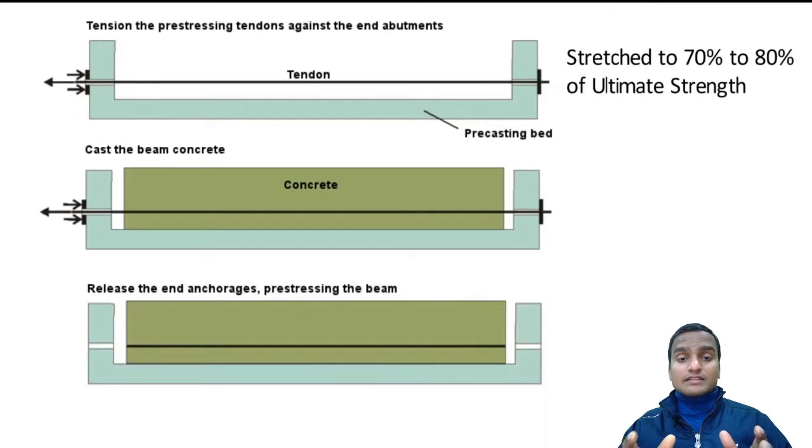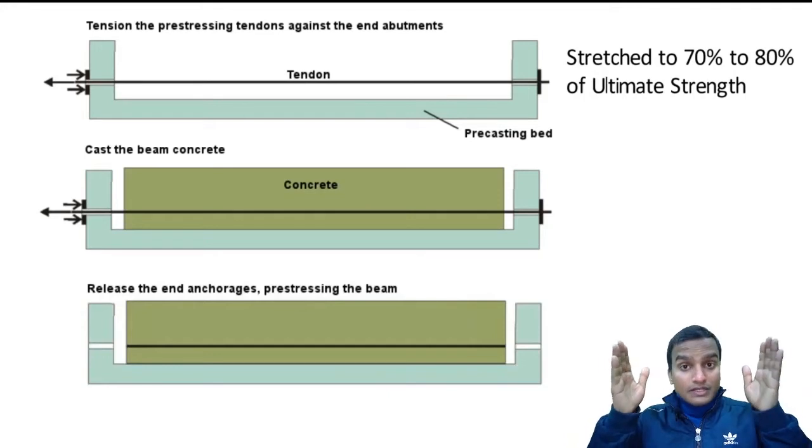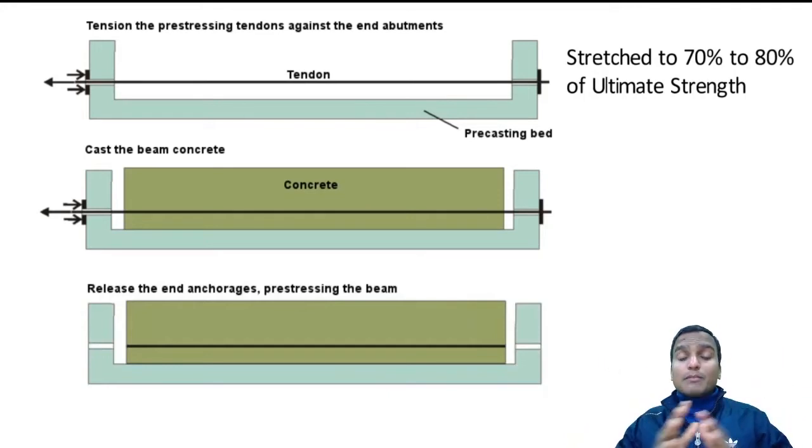After curing is done and the concrete is set, now we cut the ends of the tendons, and the beam is said to be pre-stressed concrete. Here the tendon bars are stretched with certain tensile forces. When the concrete is completely cured, this tensile force in the tendon is resisted by the concrete by development of compressive forces even at the bottom. Why are these compressive forces developed?